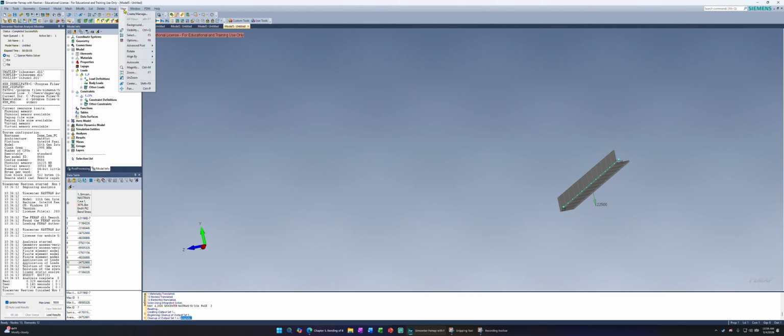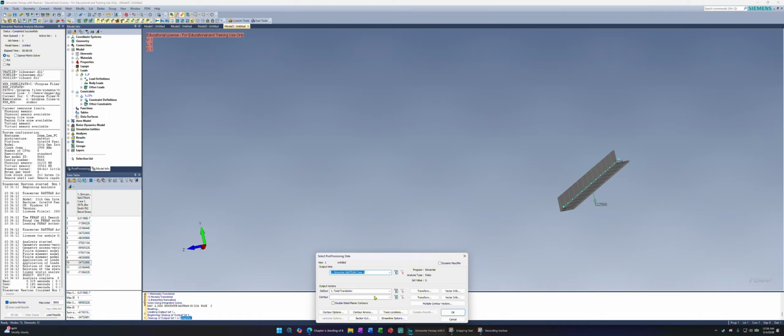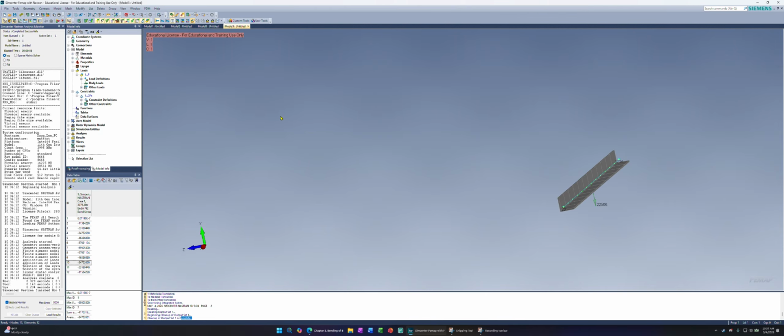See here, we want to look at our post-processing data. So we have a button here that does that for us. So post data, and we want to make a contour of this. There's a ton of them here. Remember when I said we should remember that 0.2? Look, there's 0.2 right there. There's 0.2 shear force, different points that it says they're on. This right here is our bending stress at 0.2. So we'll choose this one. I don't know what the difference is between end A and end B, but let's just go with this one for now. So we'll hit OK.